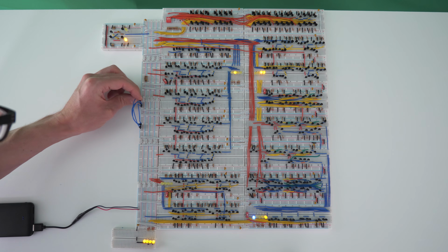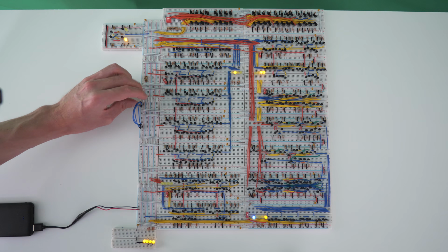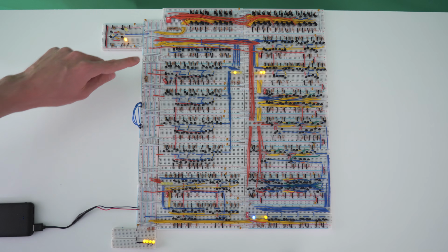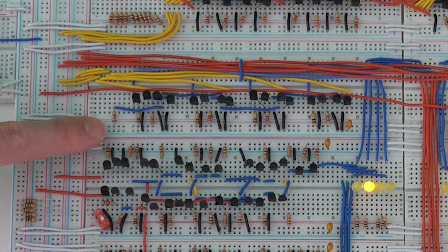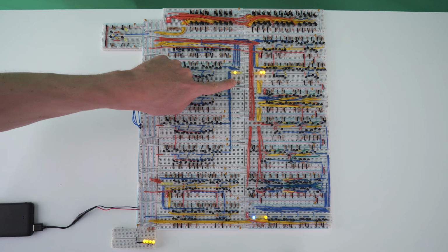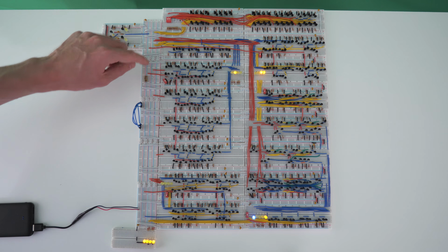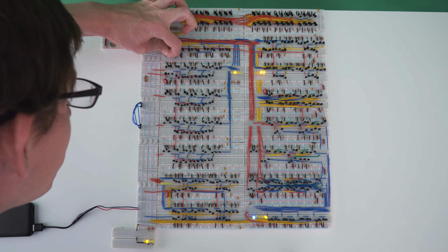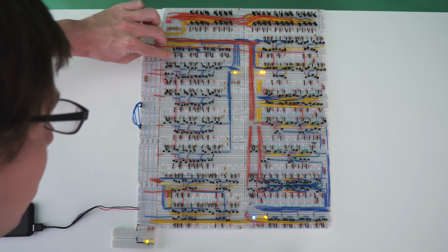So now we need to get the value from our A register. And we don't actually have the output from these tri-state buffers hooked up to a switch, but we can make it so that this resistor, rather than being connected to positive, goes to ground, which will send the output from this A register to the data bus. So let's do that real quick. Instead of being positive, we will send it to ground.